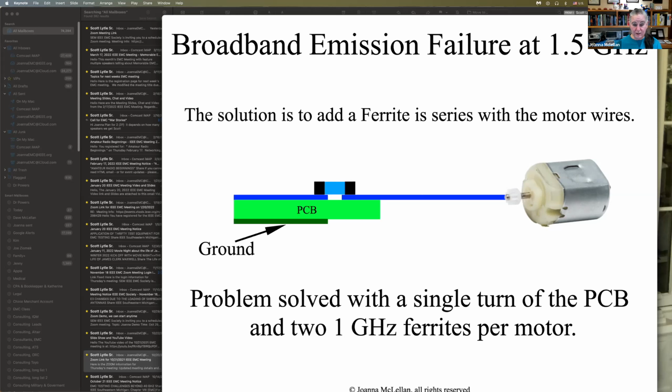And you do that really simply by looking at the characteristic impedance of every single transmission line. People that don't understand transmission lines think of it as just a wire. Okay, it's not a wire, it's a transmission line. Calculate its characteristic impedance, and if it's anywhere near 377 ohms of free space, redesign the physicality of your device so the characteristic impedance is low enough to keep the fields inside the transmission line.